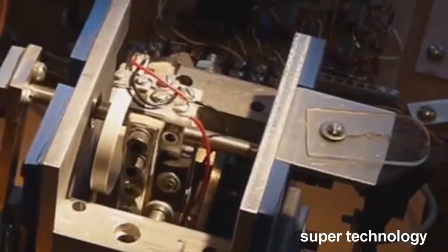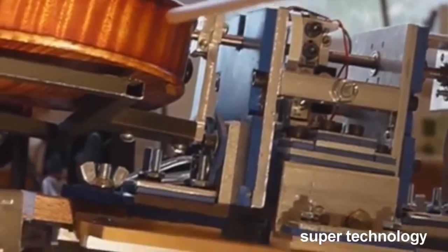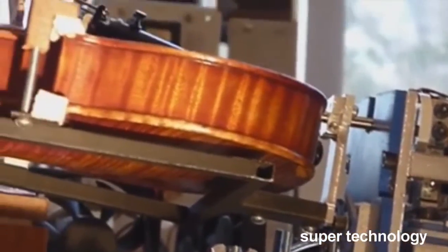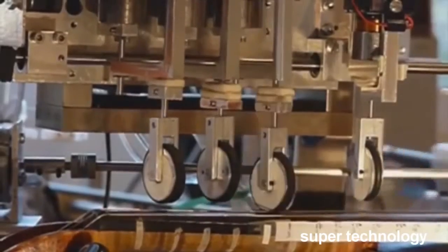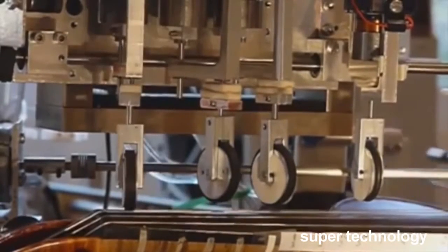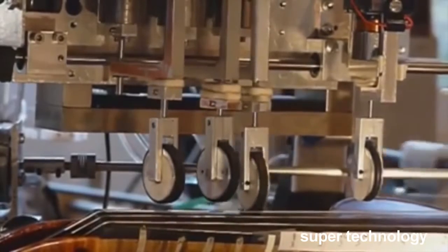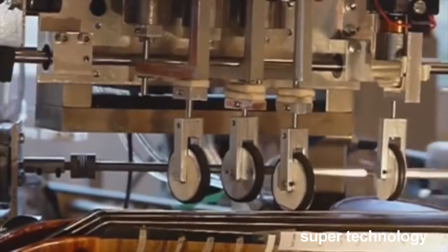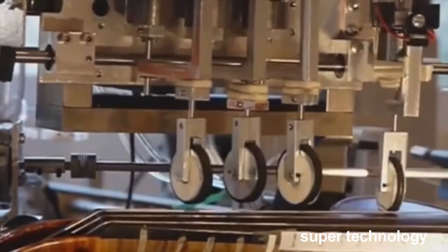And this actuator determines which string is bowed by moving a very light metal cradle to which the violin is clamped. The carriage holding the four fingers usually is stationary. Its motion is confined to playing high notes on the top string. The fourth finger reduces the maximum carriage motion needed for very high notes.